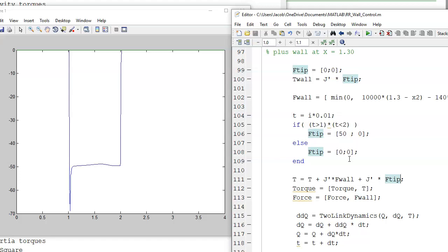The next lecture is kind of a recap, but what we have so far is we can do forward kinematics, given a robot, define its reference frames, then calculate the tip position. Inverse kinematics, given the tip position, calculate the joint angles. I can come up with the dynamics using Lagrangian formulation. I can control the robot either in XY coordinates using Jacobians or joint angles using PID controllers. And I can come in contact with a surface and maintain forces against the surface using Jacobian transpose. And that wraps up 761 robotics.